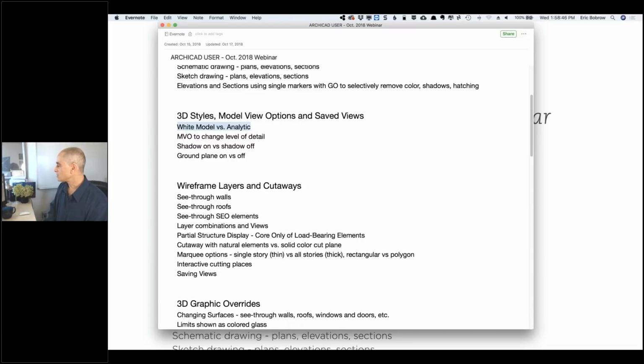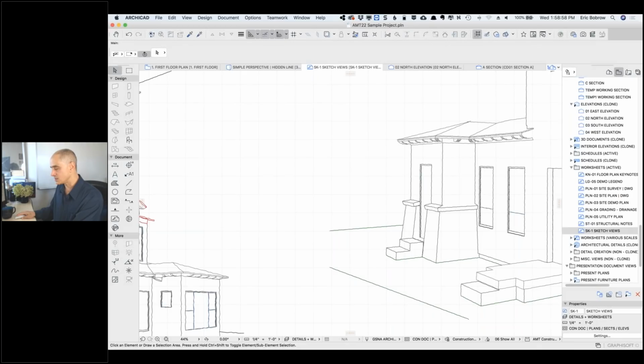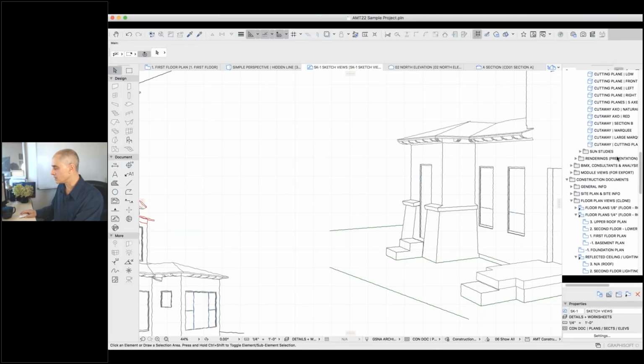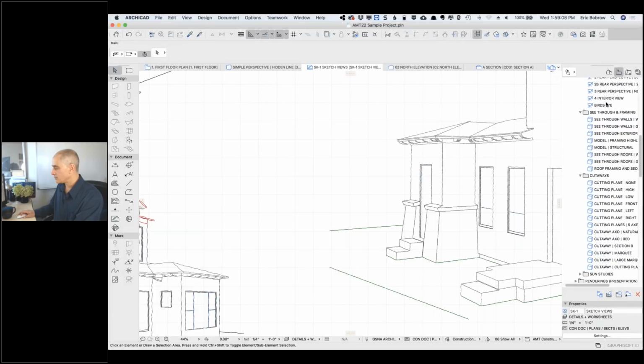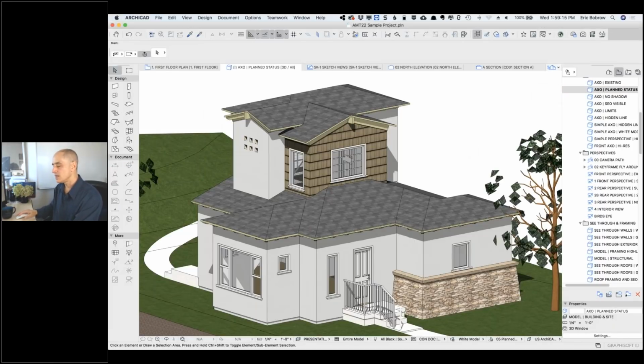Ricardo, hey Ricardo, can you set a layer combo once you've gotten the drawing to show just the layers you've displayed from the 3D document? Okay, so let's talk a little bit about best practices for layer combination. I'm in ArchiCAD here. If we were taking a 3D view, here's just our simple 3D view, and I say, you know what, I don't want to see the trees. So I go to the layer combination.